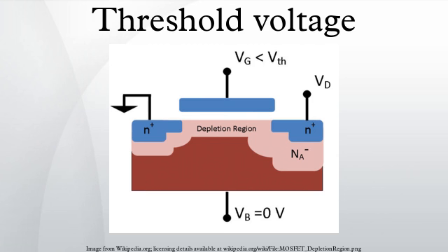In wide planar transistors the threshold voltage is essentially independent of the drain-source voltage and is therefore a well-defined characteristic, however it is less clear in modern nanometer-sized MOSFETs due to drain-induced barrier lowering. In the figures, the source and drain are labeled N+ to indicate heavily doped N regions. The depletion layer dopant is labeled NA to indicate that the ions in the depletion layer are negatively charged and there are very few holes. In the bulk the number of holes p equals NA, making the bulk charge neutral.